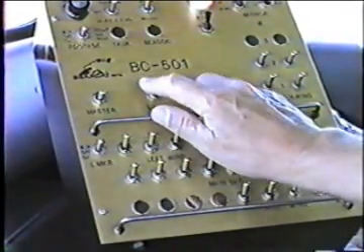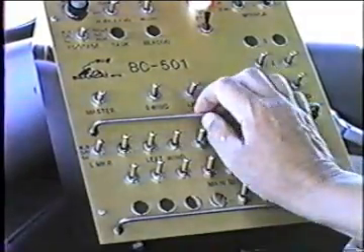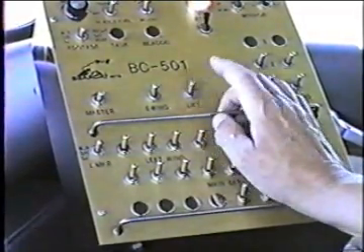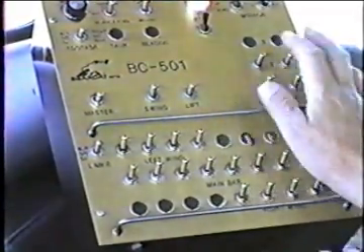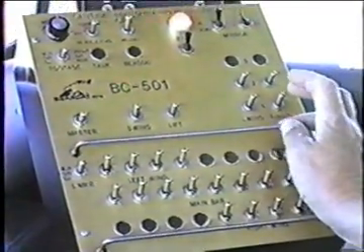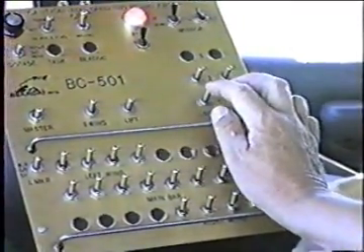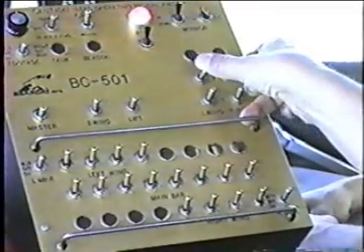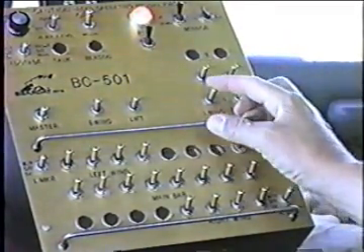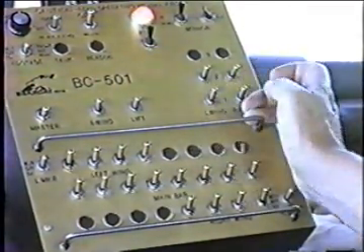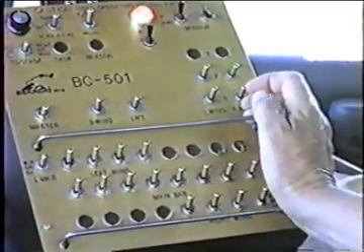Spray bar swing, momentary sideways just as it was at the rear. Lift is momentary up and down. And the wings. This particular truck happens to be equipped with a double folding wing, so it has a pair of switches for each wing. Top switch is the outer wing, bottom switch is the inner wing, and of course left and right.